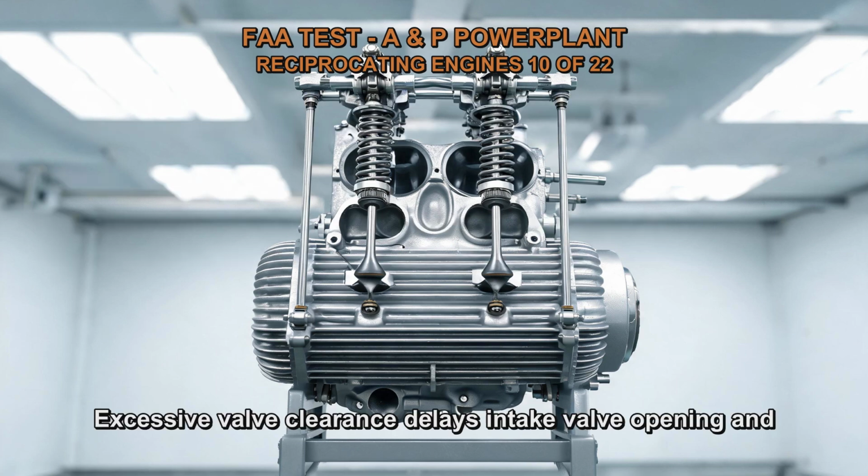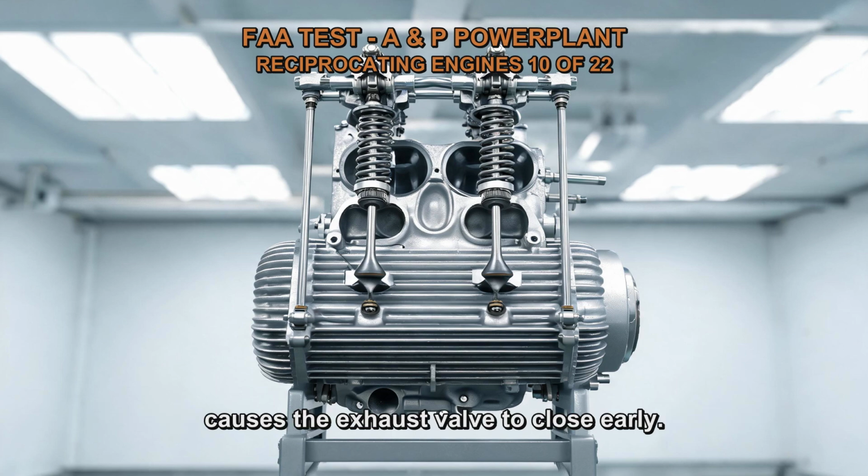Excessive valve clearance delays intake valve opening and causes the exhaust valve to close early. This shortens the valve overlap period. So the correct result is a reduced valve overlap period.